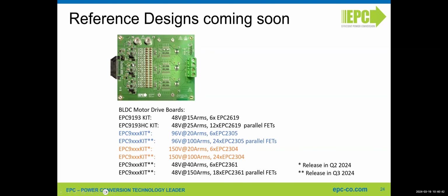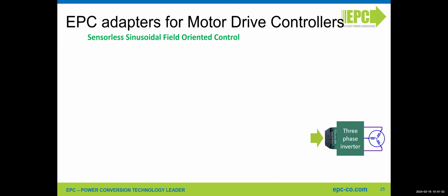And if you look at all these reference designs, they come with the same connector here, because here there's a power inverter, there's current sensing, temperature sensing, voltage sensing, DC bus ceramic capacitors, and overcurrent protection. Okay, all the boards share a similar architecture. And then how do you test the board? So the board looks like this, a 3-phase inverter going to a motor and a connector.